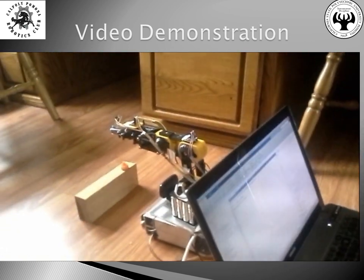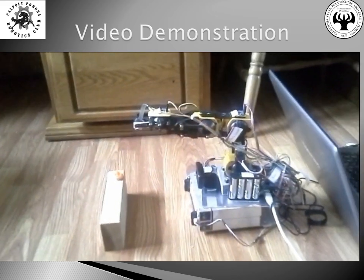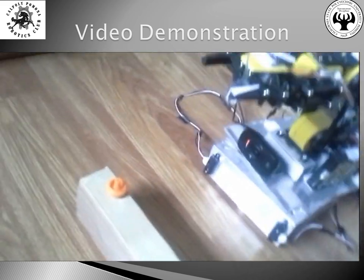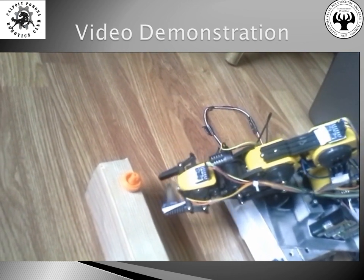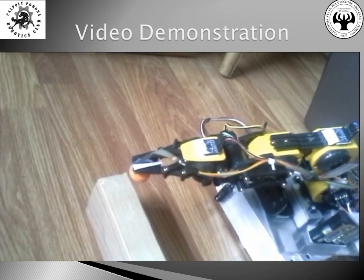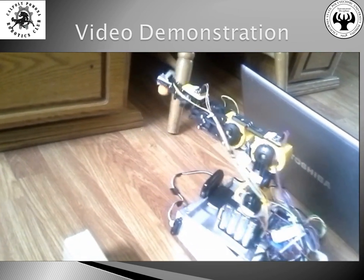The master program first starts out by having the arm in a default set position. The camera then takes pictures of its surroundings. Once the target object is located, MATLAB then creates angular set points for the links, and the control algorithms are executed until the target object is reached. The gripper then grabs onto the object, and it is then discarded off to the side.